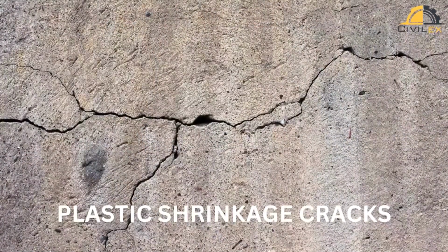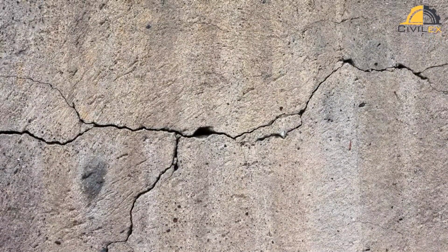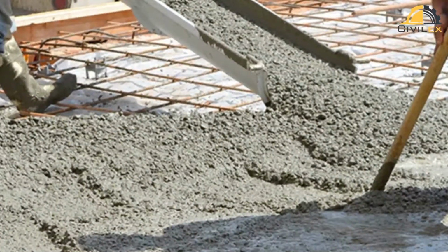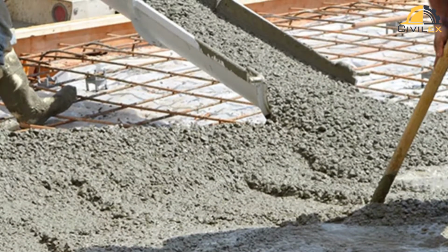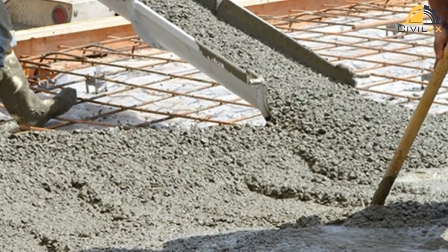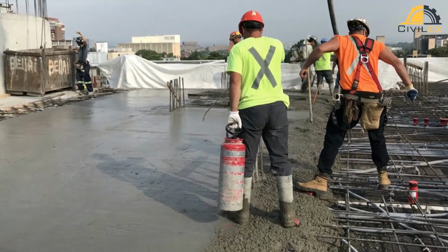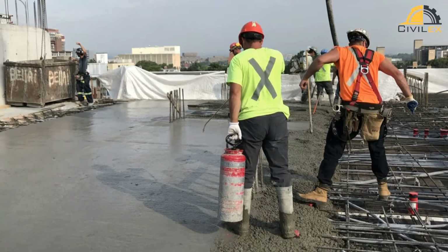Plastic shrinkage cracks. These are narrow, shallow cracks that occur during the first few hours after concrete is poured and while it is still in its plastic state. They are caused by the rapid evaporation of water from the surface of the concrete, which can be exacerbated by hot or windy weather conditions. To prevent plastic shrinkage cracks, concrete can be covered with a damp cloth or sprayed with a curing compound to slow down the rate of water evaporation.